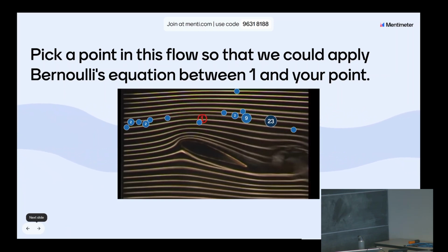Are there any questions on that? Yep. Yeah, there's a bunch of reasons. One of them is unsteadiness. Yeah, and you could approximate the energy input into what happens on the streamline. That's basically how turbomachinery analysis often works. You say we're going to do some sort of work input with this fan, and then we can account for that in our energy equation. But Bernoulli's equation, the one that we've looked at so far, doesn't have that term in it. So that's why we say it doesn't apply.